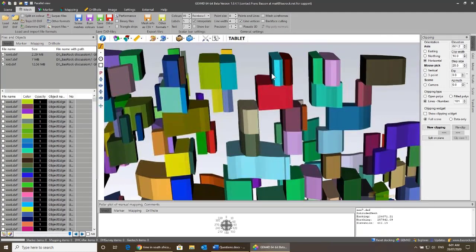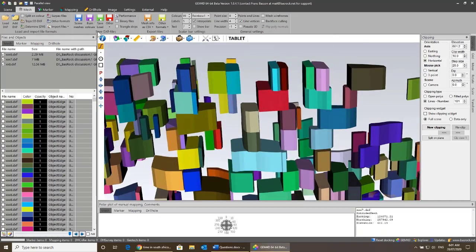The only thing to test for now is to see if the poly orientation is in the right direction. So I'm going to say backface culling, and you see I don't see any changes on the backface culling. So it seems like this file is good. So I can now save out this file and take it to Mat3D, and Mat3D should accept it as is. Or it could be a complex wireframe, and it should be fine as well.